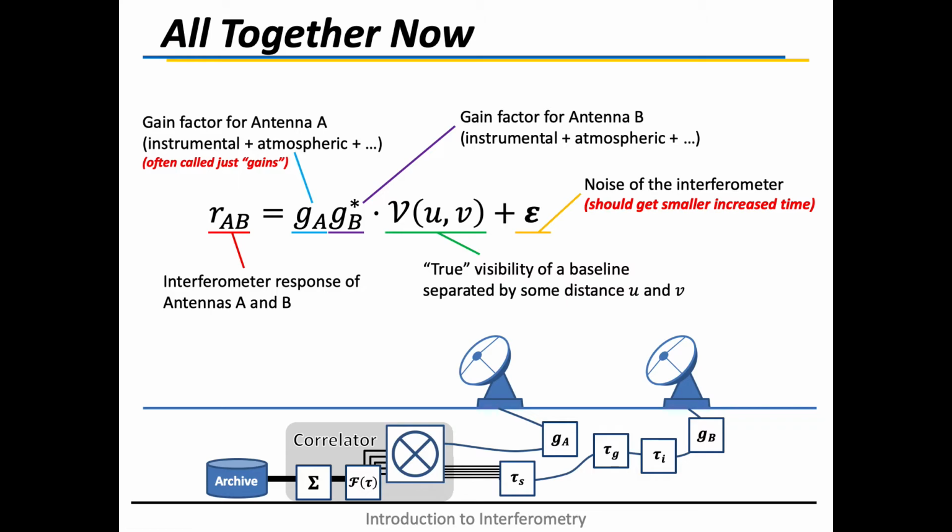But that greatly averages down the data that we have to record on disk by factors of thousands. And so rather than getting petabytes worth of data, you can get gigabytes worth of data. And this is the thing that's actually stored: the accumulated sum after some integration time, is typically what we call it. And we can only do that because all of these components, save for the noise, which should be random, should be stable at least over that interval of time.